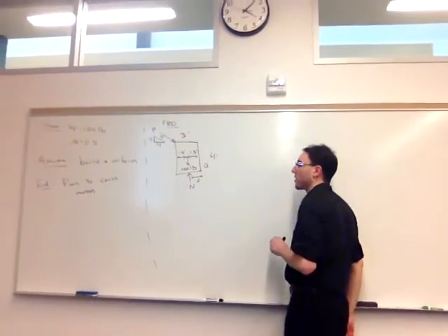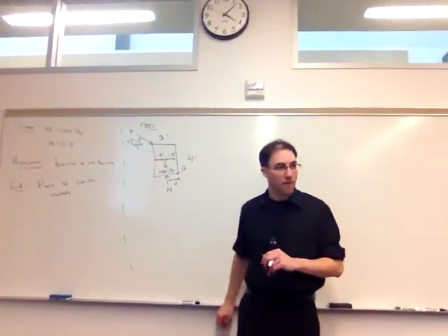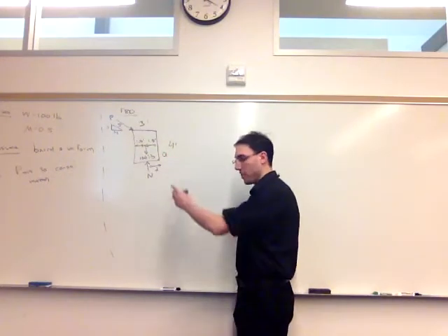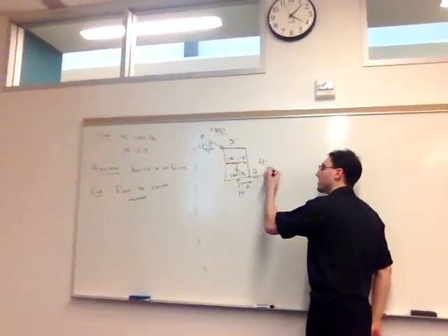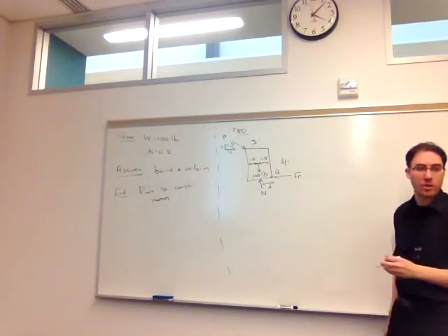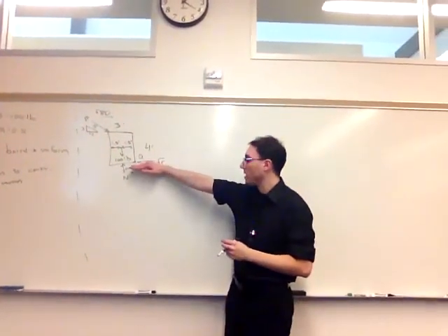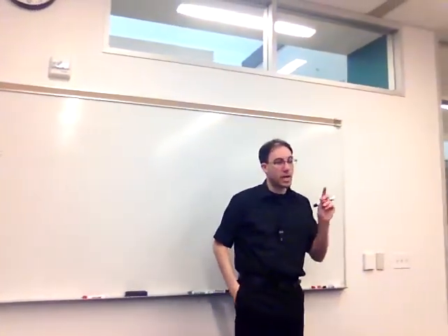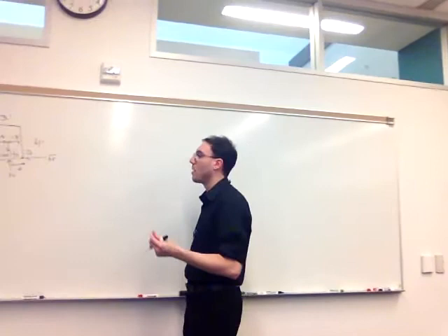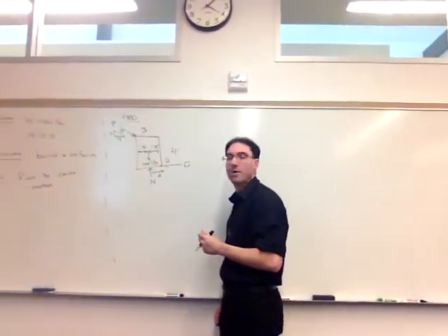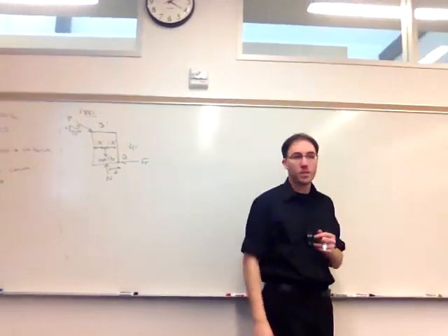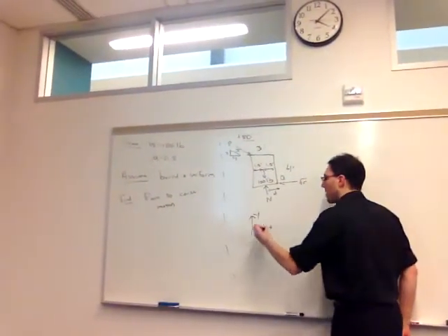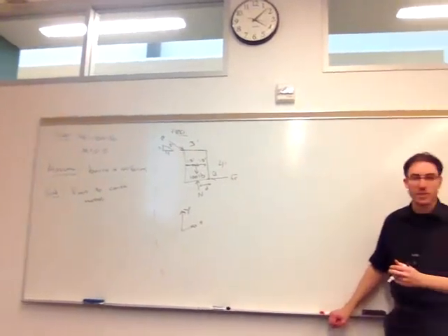And then what other force is going to be acting on the barrel? Friction force. We would think that if we push the barrel to the right, it would be traveling to the right, which means that the friction force would oppose that motion and point to the left, parallel to the surfaces they're in contact. So we have an unknown normal force, an unknown distance away from a pivot point, an unknown friction force, and we don't know how hard we're pushing the barrel. So this is our complete free body diagram once I have the coordinate system here.